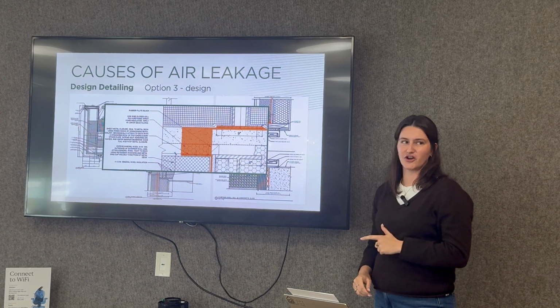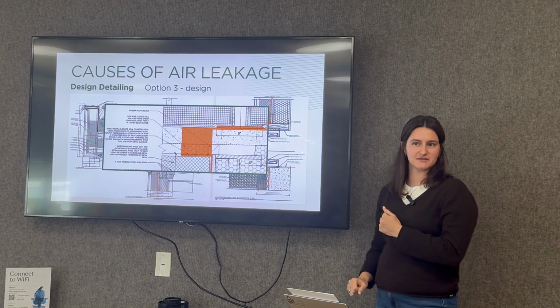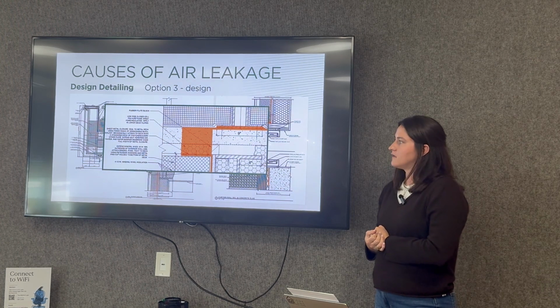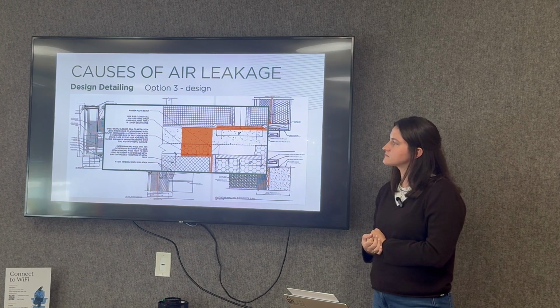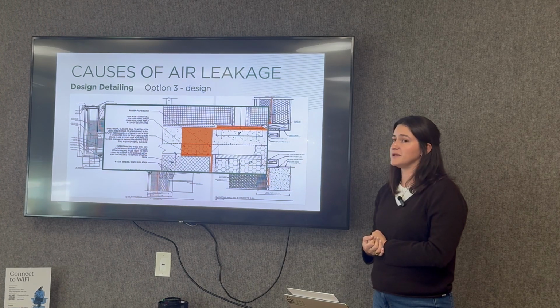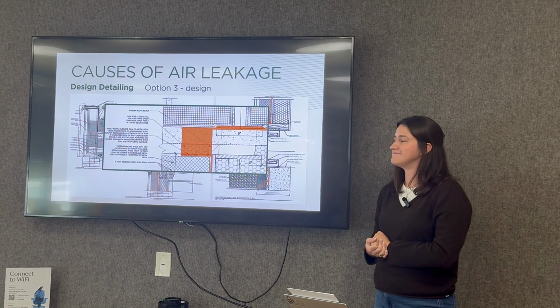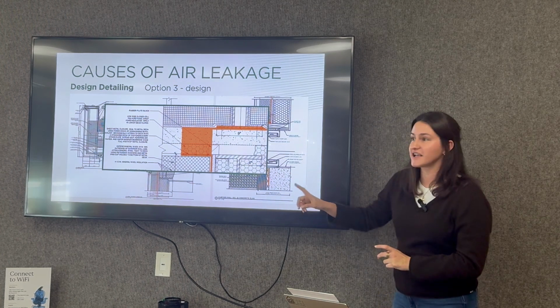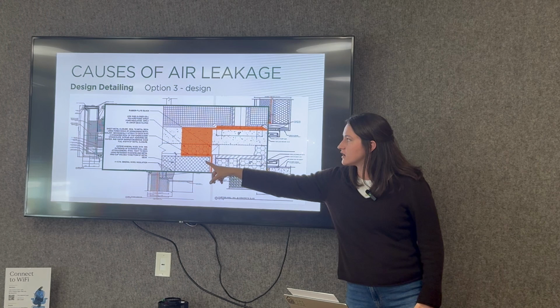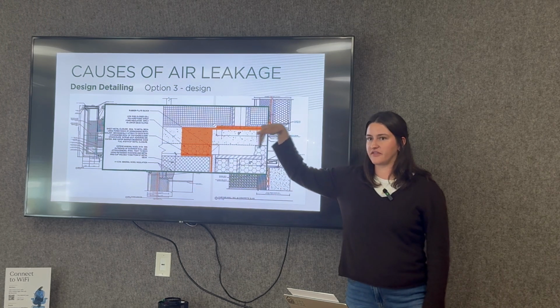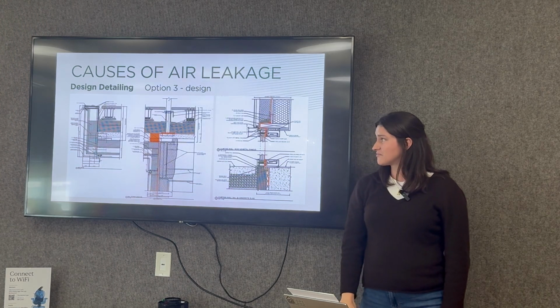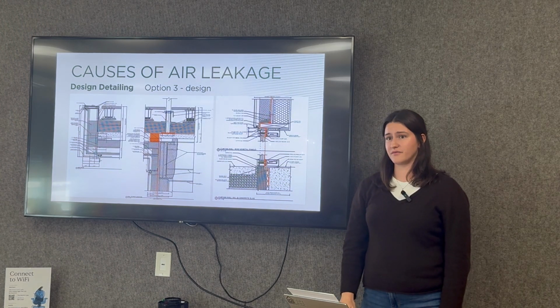Anybody have any questions on this sort of thing before we talk more about design? Did the rubber flute block cause any fire problems? Building's still being constructed, so I don't know. I couldn't tell you. I wouldn't think so, because we have mineral wool up here, and then mineral wool at the extent of your soffit, and this detail is occurring probably 3 feet or more inboard of that.